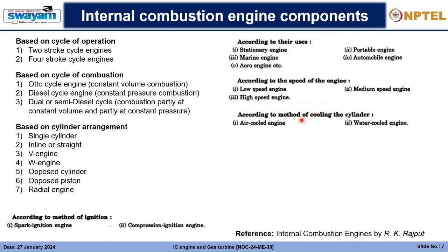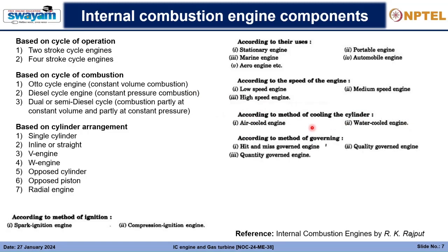Heat in the cylinder walls is actually caused due to the combustion inside the engine. Motorcycles generally have air cooled engines, but in cars, four-wheelers, that is generally not the case. There is a radiator arrangement and a completely separate cooling system, and there the water cooled engine is produced. There will be a water jacket covering the entire cylinder, and the water which is getting heated up is eventually cooled by the air passing in the radiator. So we'll get to know about all this.